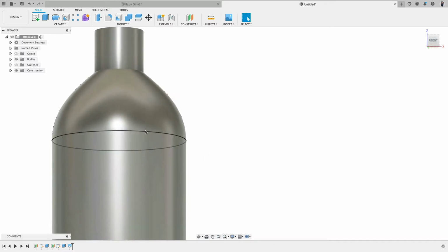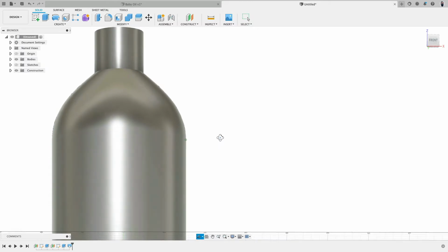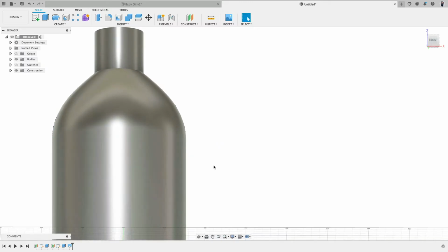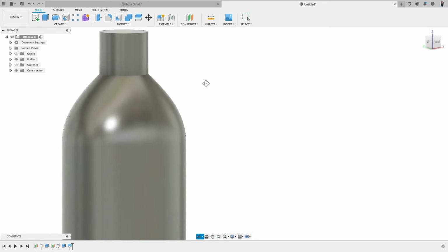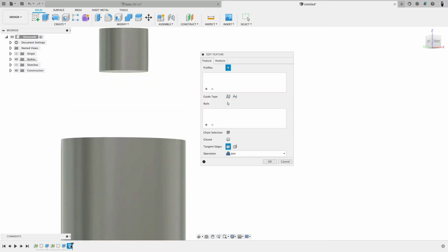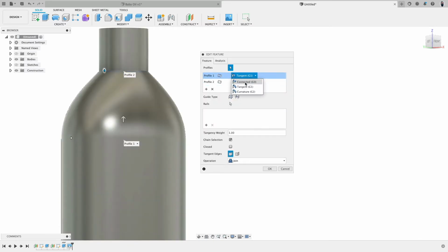Do you see, actually there is an edge here? There, you can even see that, because the highlight now goes from a cylinder instantly to a highlight of this blend surface. And that is why in design I hardly ever use G1, basically exclusively use G2. However, G2 is more complex to calculate, so very often I set it to G1 and later go to G2.